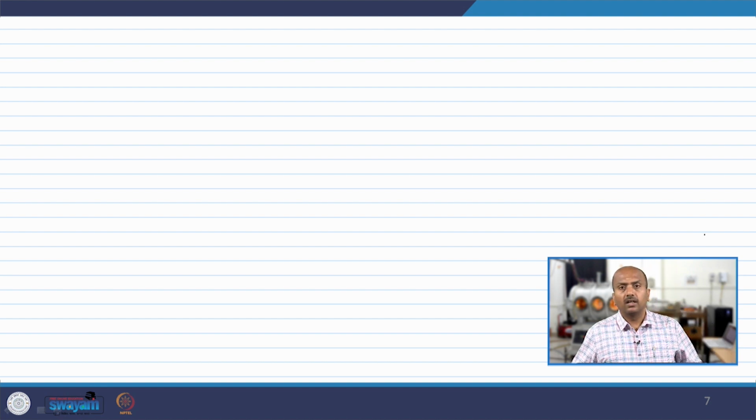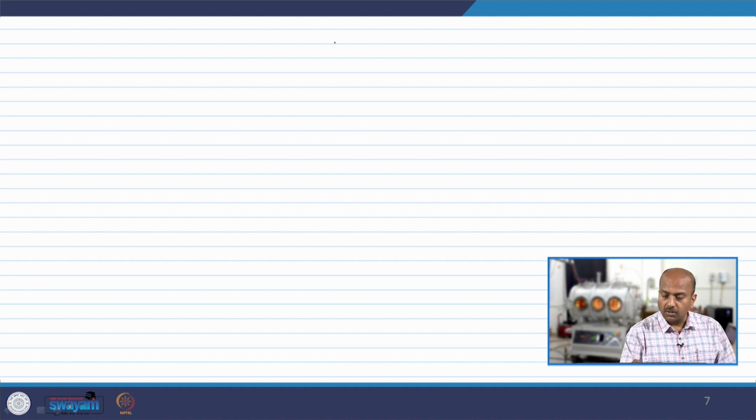So, for the density to be maximum at the center and 0 on either sides, because the solution that you have assumed is sinusoidal in nature, you want this condition to be maintained at plus minus L: square root of D_A tau, x you are putting as L, okay.